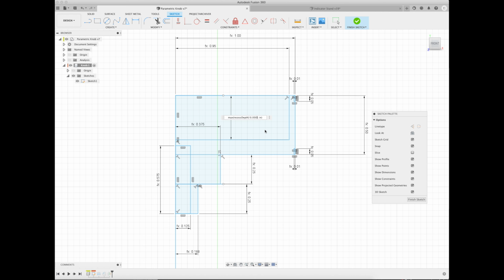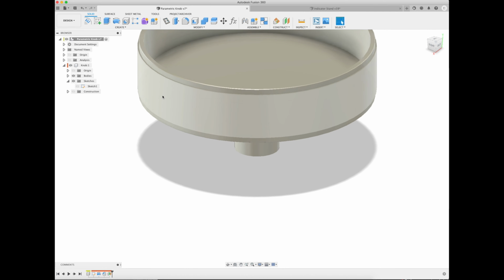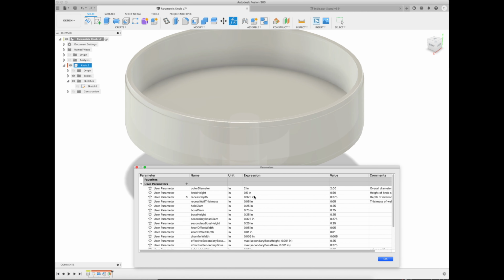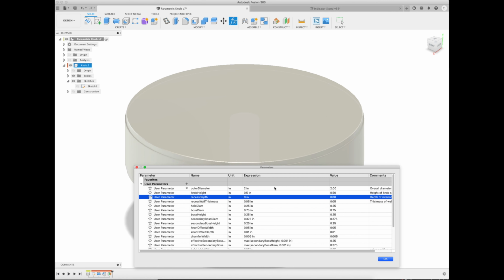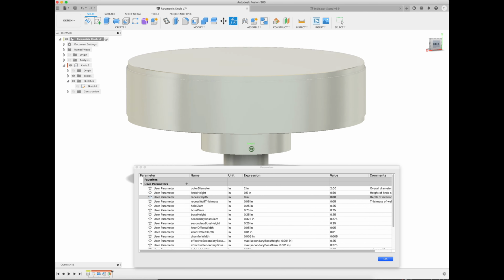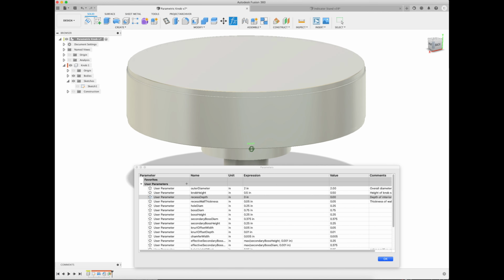So if you want a flat knob, it's actually going to show up as a 1,000th recess, which is fine for me because I'm manually milling these, or manually cutting them on the lathe. But if anyone knows a different technique, I think here I demonstrated that you can actually take that down to 10,000ths of an inch, which is imperceptible.